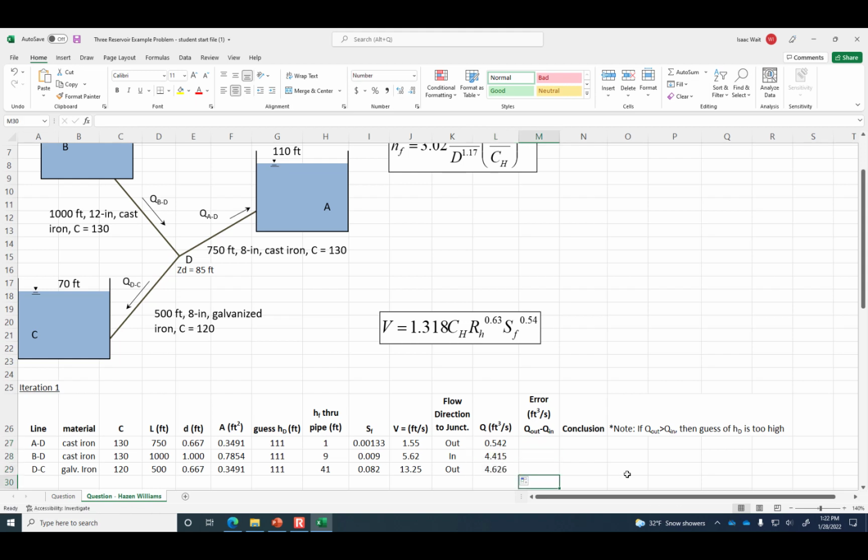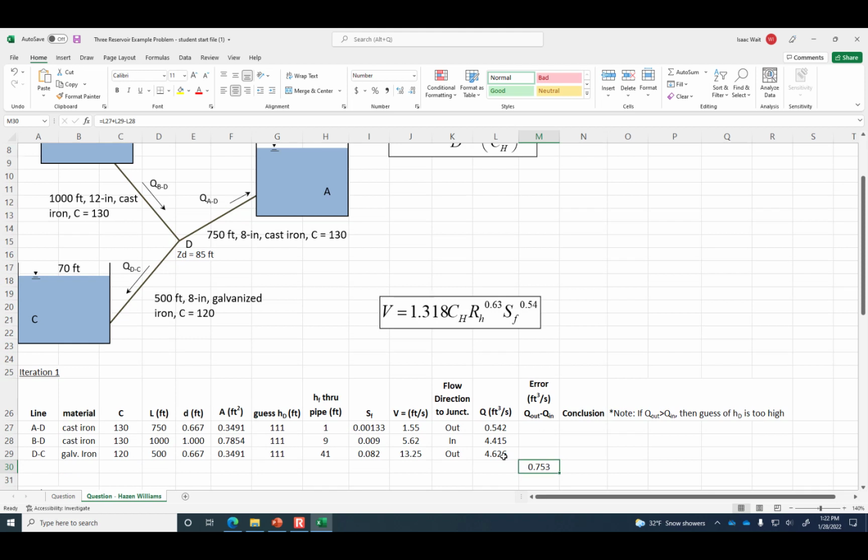And then down here below, in the next column to the right, we want to have all of the out minus the in. So there's two outflow terms. So we're going to have this top outflow plus pipe DC outflow, and then minus the inflow. So if continuity is honored, then in minus out will be 0, because we know there's no accumulation of water at D. D is just some enclosed junction. There's not a separate storage tank at D. So in equals out at junction D.